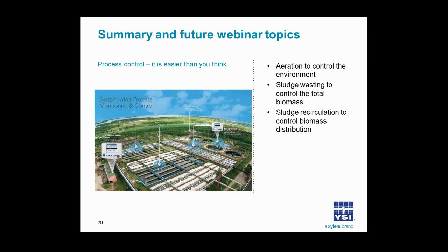But for the continuous measurement we showed in the slide there, unless you happen to be measuring in the effluent, the zero is not that important. You really would probably benefit by calibrating within your normal operating range. So if zero is near your normal operating range, then yes. But otherwise, I would say probably not. Thank you.